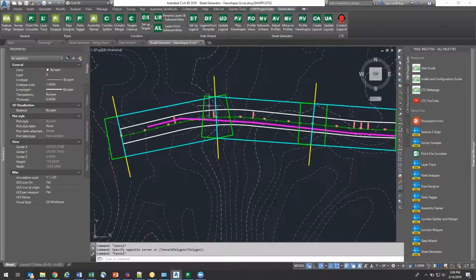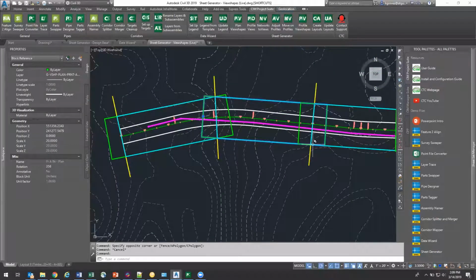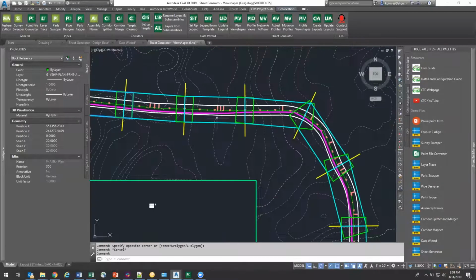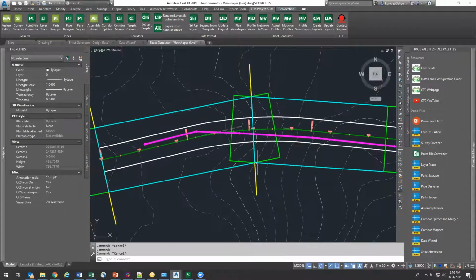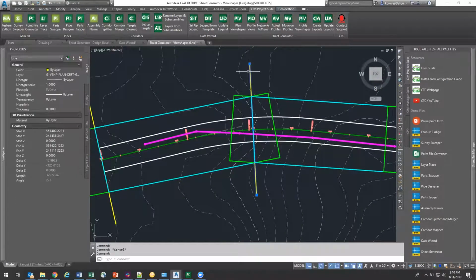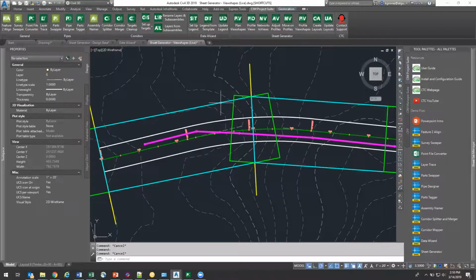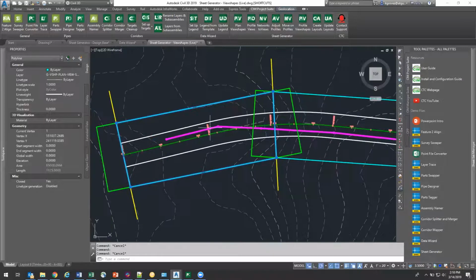And then as these green plan view shapes get put down along the drawing, based off of a variety of criteria, we'll notice that they've got some overlap. Where these view shapes cross each other, we get this match line, which is pretty typical for how the native view frame tool works. But then it's automatically going to take its first guess, and we can redo this if we want, and dynamically trim. That's what this cyan line is. It's everything along our maximum viewable area trimmed within our match lines.